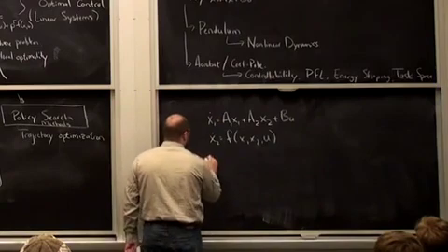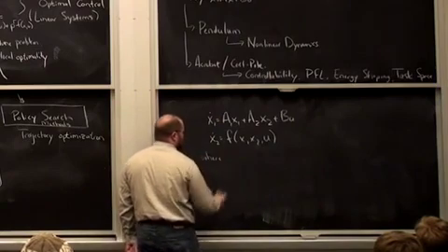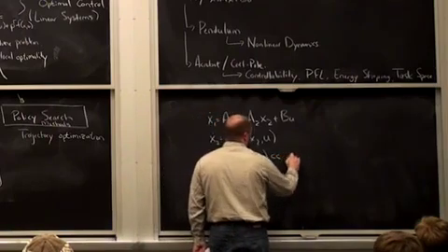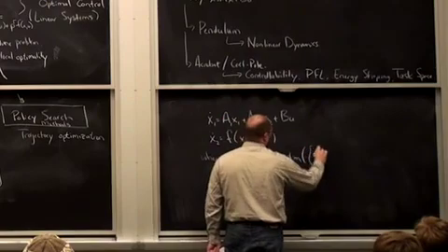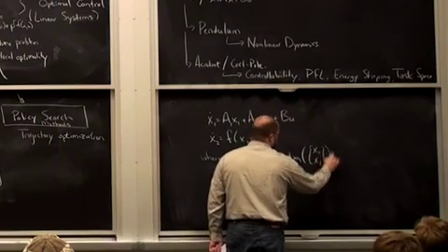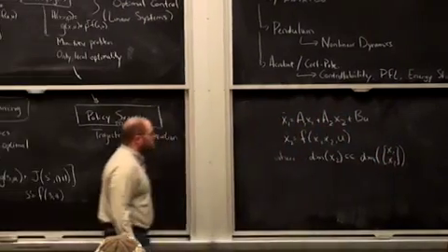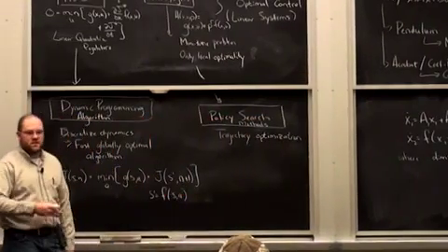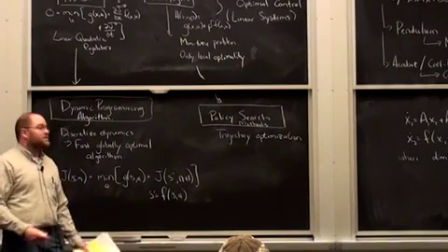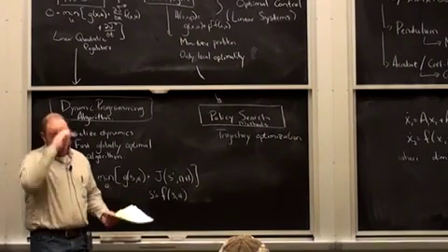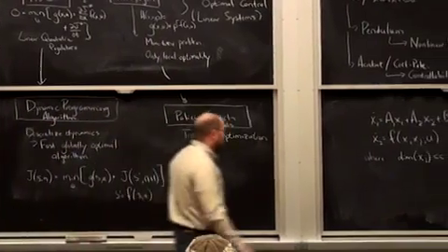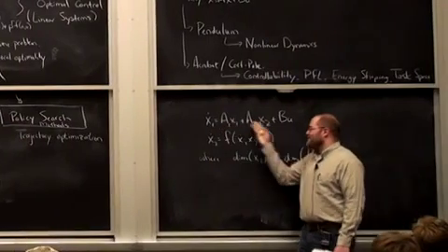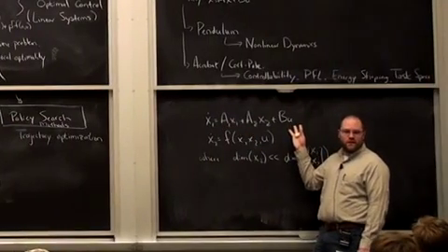where let's say the dimension of x2 is much, much less than the dimension of the whole original system, which is what I get. That's the result I would get from doing a partial feedback linearization, where I have, let's say, for little dog, 5 degrees of freedom and 4 actuators. Then I'd end up with one very nonlinear thing, and then a bunch of very linear dynamics after doing a partial feedback linearization.